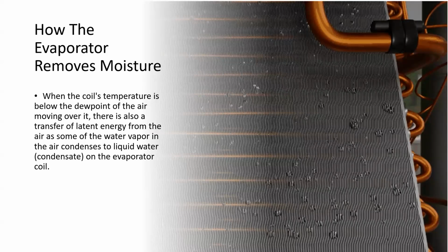That could be we put a 2-ton unit on a 5-ton blower and never adjusted our airflow, or could not achieve the right airflow. Our delta T might look proper, our pressures might look proper, but if we did our delta T with dry bulb, which we usually do, and we didn't actually measure what our wet bulb was, we may not be removing both loads in the home. Total heat is sensible and latent. Most of the time, latent is much lower than your sensible load, unless you're in somewhere like Louisiana or Alabama, in the South, where it's 100% humidity and a 100-degree day, which just sounds awful.